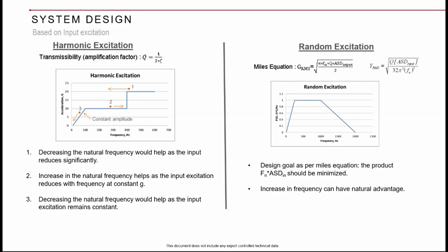So in such cases, if you reduce the stiffness of the system, you know the displacement driven problems, right? When you apply force, you need higher stiffness. When you apply displacement, you have to reduce the stiffness to have lesser resultant forces in the system. So the objective is not reducing the frequency here, but with the reduction in stiffness for the same double amplitude input, your stresses will be less. We'll see some examples.